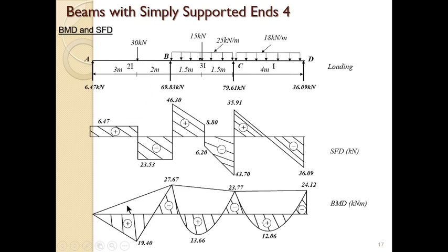Now, again, for us to know this point, which is directly where the maximum load is, it's all going to be this plus this divided by 2, because that mid-span is not the middle. In this case, you have a load of 27.67 here, you have 0 here, and the thing is moving serially. So at this point, which is 3 meters from here, you're going to use the concept of similar triangle or the concept of interpolation to find the magnitude of moment at this point. So if you do that right, you're going to have 16.6.